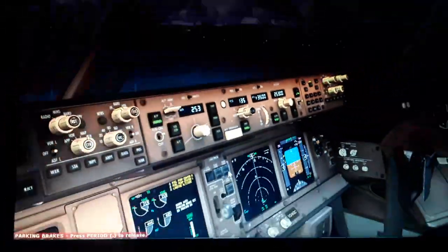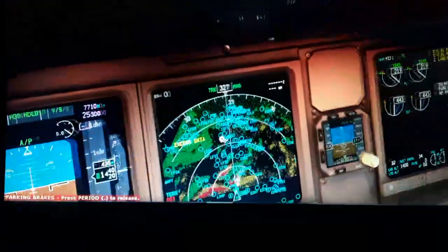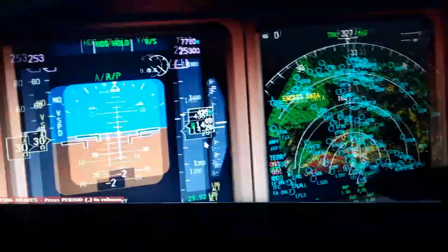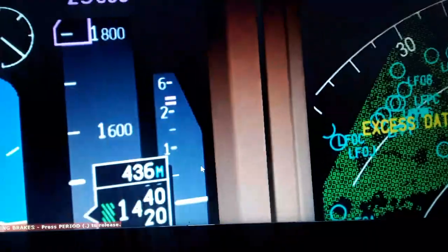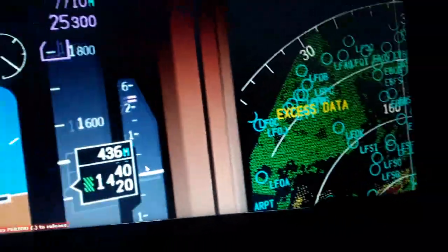So you have the +3,500 feet per minute, and this is gonna give you a climb rate of 3,500 feet per minute with this vertical speed mode, target airspeed, target altitude, and the pitch. Also this is gonna be displayed over here with the purple arrow indication. So we have a few more minutes to go. So this is all in all the modes of the autopilot.